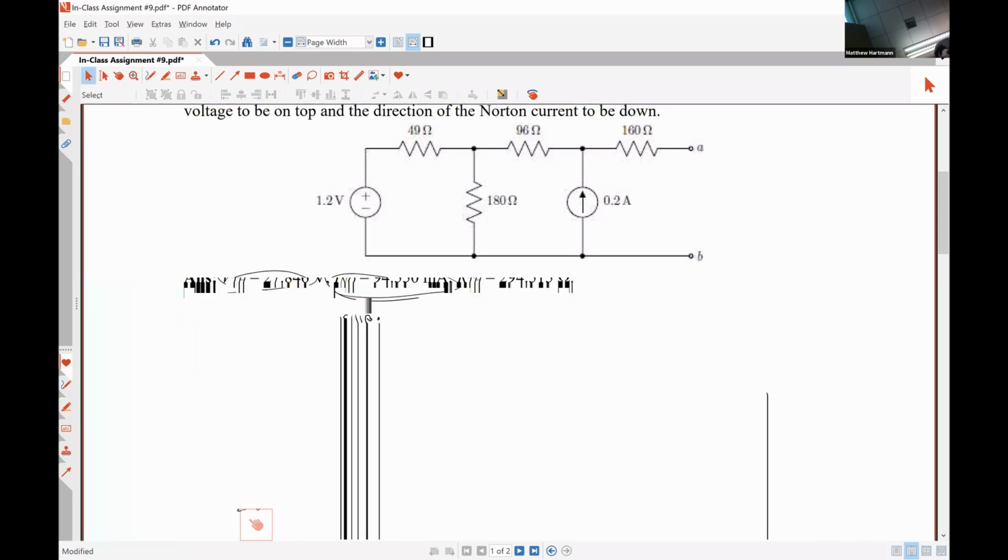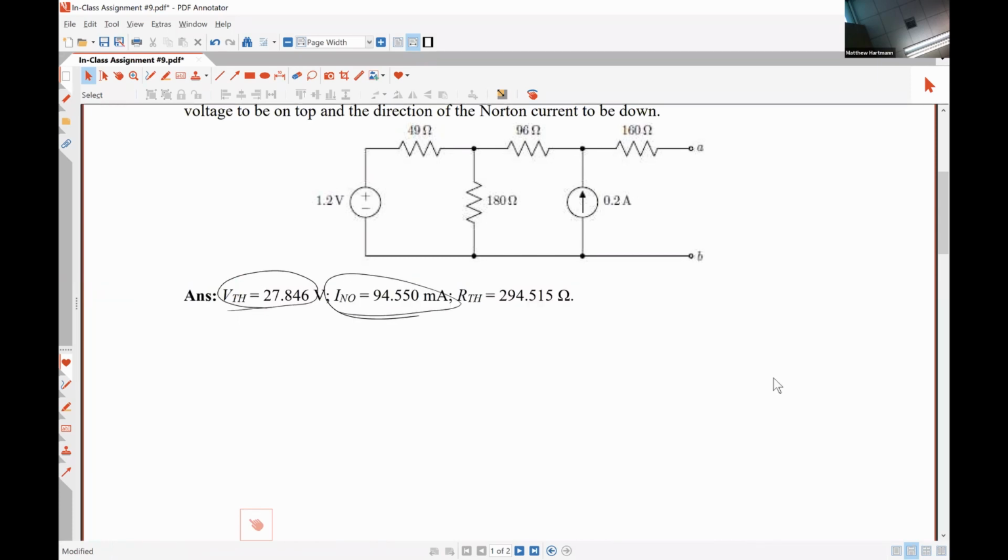So who among you remembers how to turn off a voltage source? You put it as an open circuit. So to turn off a voltage source, we want to make sure that the voltage is 0. Are we guaranteed that the voltage drop over an open circuit is 0? No. So you short it then. Right. So to turn off a voltage source, you short circuit it because we know that the voltage drop over a short circuit has to be 0.